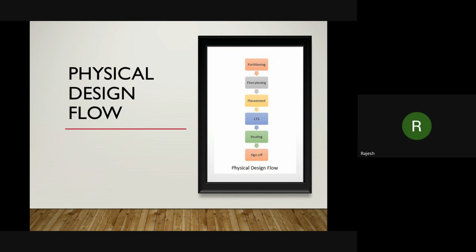Okay, and as I told, they will give you one circuit. That circuit consists of all the standard cells. Standard cells are nothing but AND gates, OR gates, NOT gates, all the logic gates, right? Not only those logic gates, there will be some bigger cells also, which we call macros. Macros are already predefined, physical design was already done for those small blocks. So we need to place those bigger cells first. The macro placement we will do during the floor planning. The placement of the bigger cells defines how the remaining cells will be placed inside your chip.